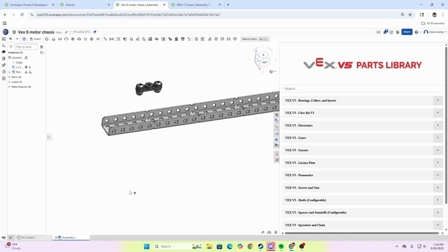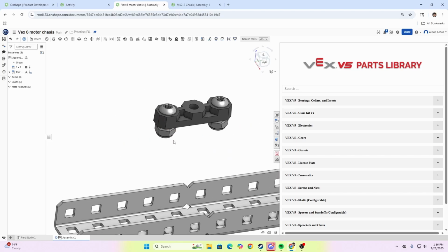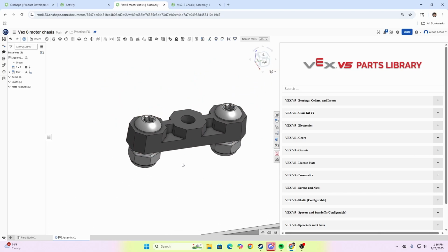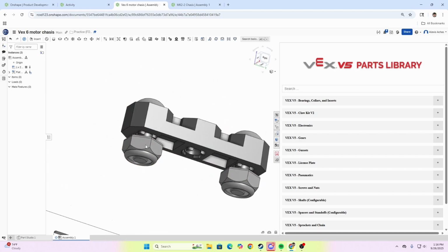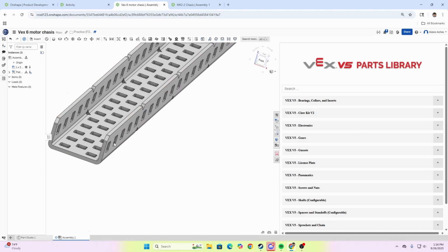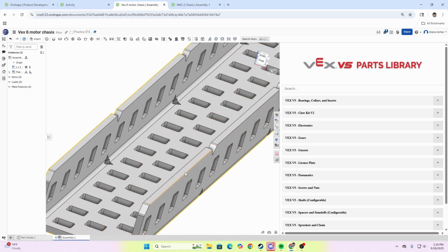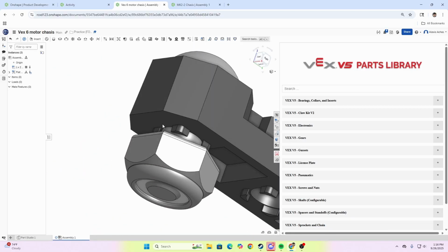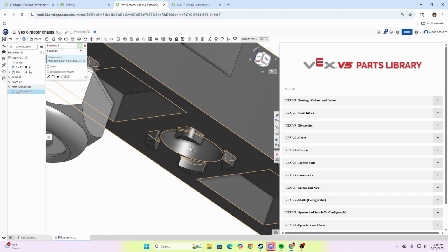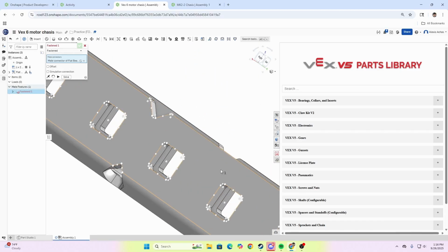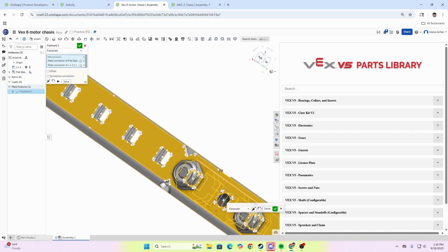If you can't find your part, look for the dot. It already has this bearing with screws already in them, and this gap right here is basically the same gap right here. It's the same thickness as the metal. All we have to do is press insert, grab the middle one, click on the center, and then insert it anywhere we want to.